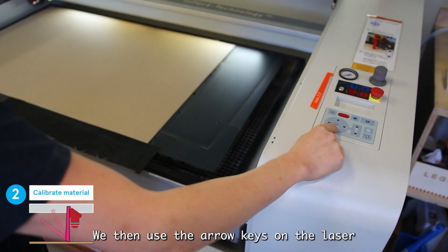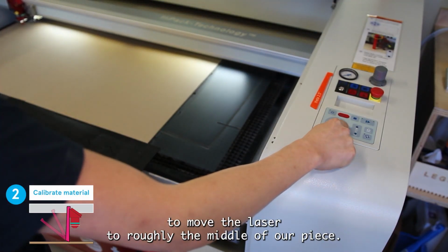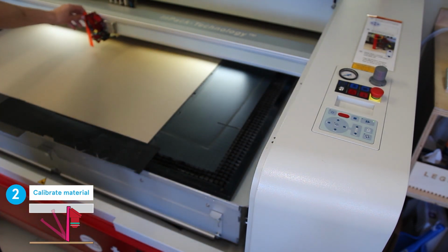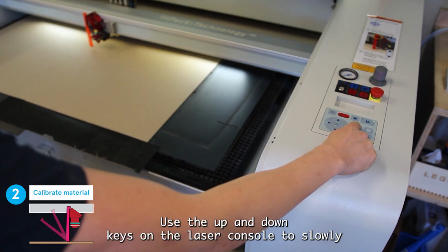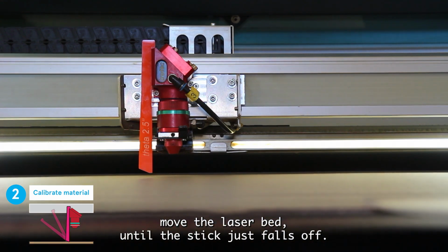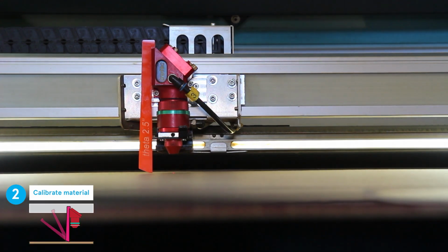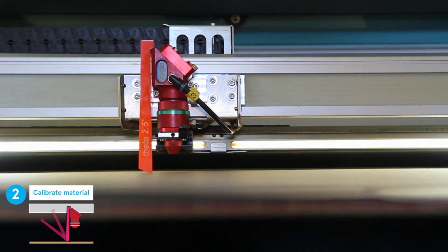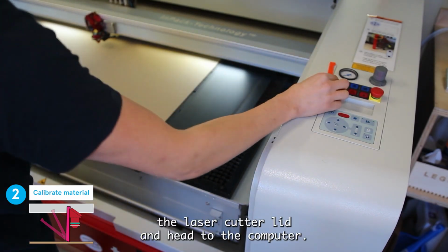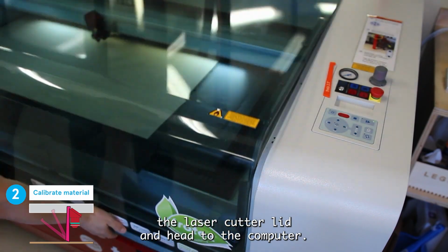We then use the arrow keys on the laser to move the laser to roughly the middle of our piece. Use the up and down keys on the laser console to slowly move the laser bed until the stick just falls off. Close the laser cutter lid and head to the computer.